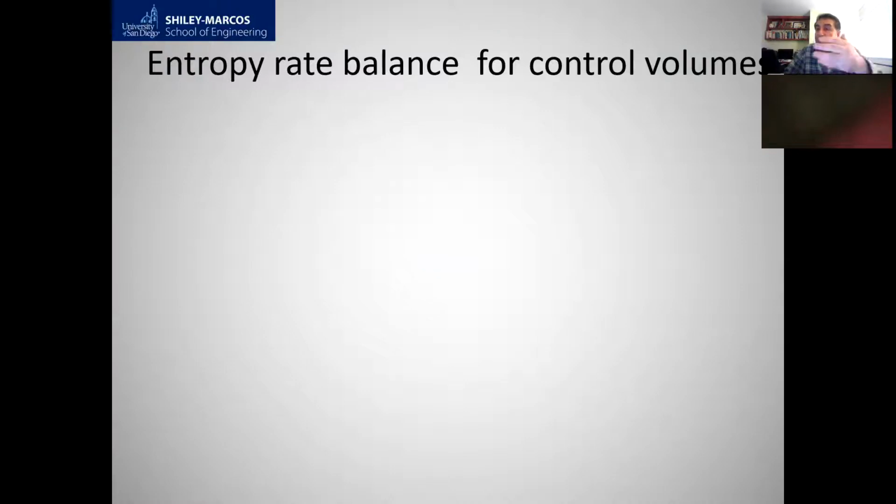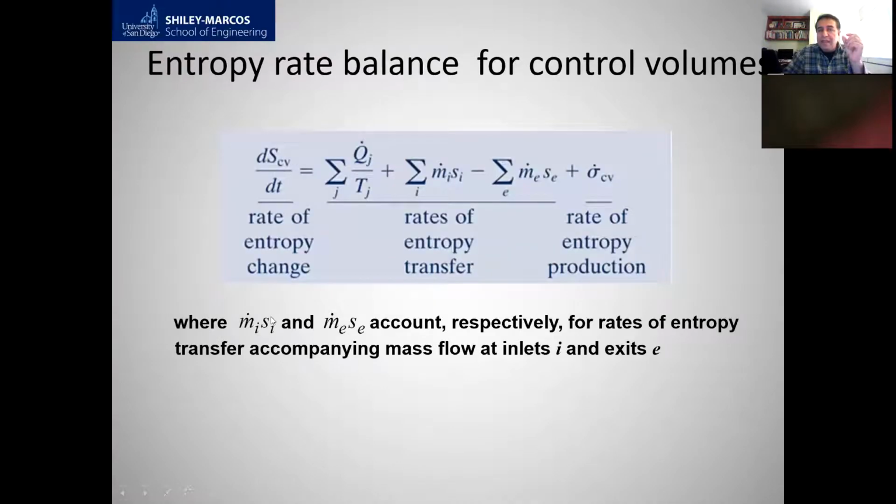Entropy rate balance. Entropy, like enthalpy and internal energy, is a thermodynamic property. For an ideal gas, you can apply the ideal gas law. But if it's a liquid, make sure you use the table. Otherwise, your result will be way off. Okay, all right. So entropy rate balance for a control volume: the rate of entropy change for the control volume is equal to the sum of all the heat transfer rates over temperature. That's the language of entropy, okay?